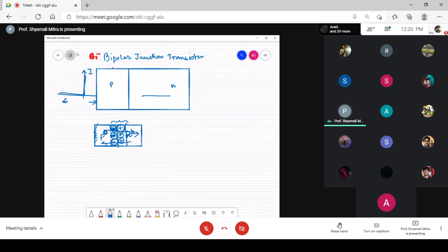When we say that a semiconductor is in thermal equilibrium, so if we can draw that again, in this condition the PN junction is applied no bias, that means no external potential is being applied to it, then the electrons and the holes crossing either side of the junction will be stopped under certain circumstances, and the circumstances are guided by the total number of these space charge acceptor ions and the donor ions that are present over there. And when the flow of majority carriers from p side to n side and from n side to p side is stopped, we say that the p-n junction is now in equilibrium.